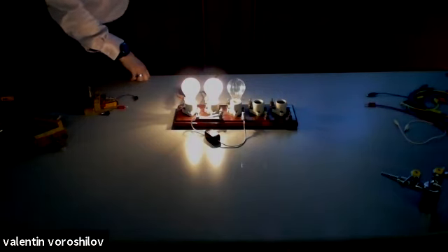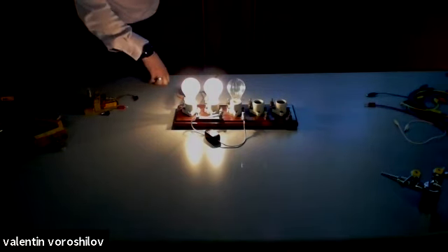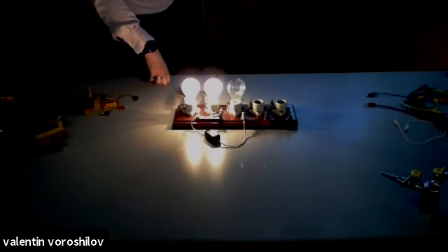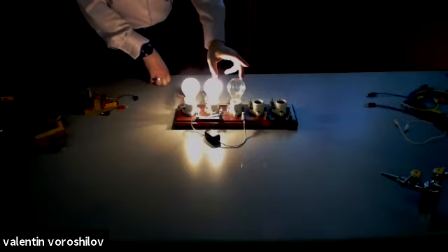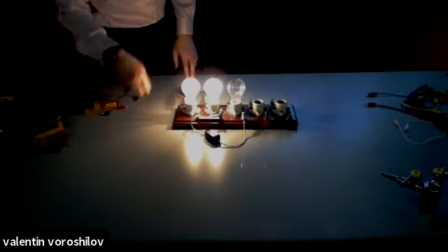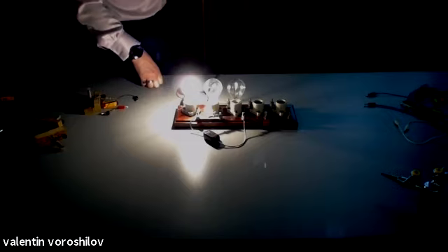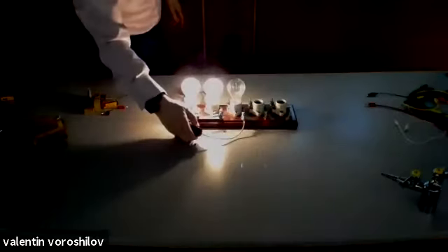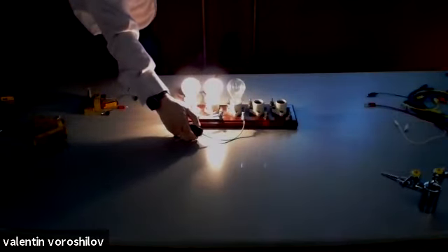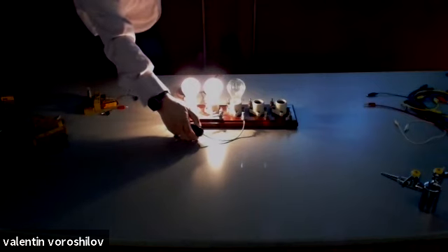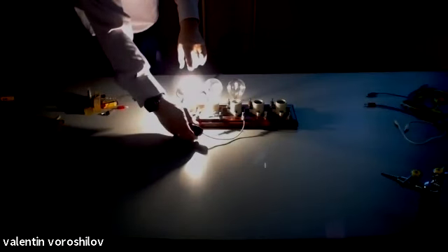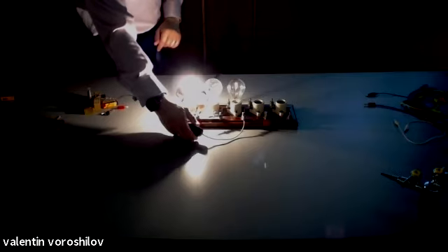This switch, if I turn it on, will connect this bulb in parallel to this bulb. These 2 bulbs will be connected in parallel. And what's happening? That bulb alone becomes much brighter. These 2 become dimmer, but equally bright. Turn it off. So this bulb is not a part of a circuit anymore. Again, equally bright, but dimmer than this bulb when the 3rd bulb is a part of a circuit.